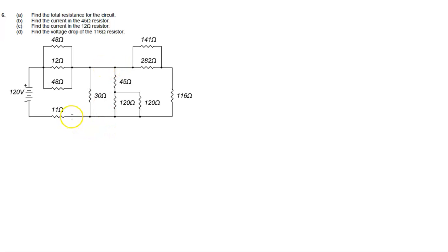And so, then he's labeled this node here as P. This one here at the negative on the battery, because there's no current division taking place there, he didn't give that one a node. In Multisim, that's the one where you put a ground there. Put your ground in there. The negative on the battery is generally considered to be a ground, right?